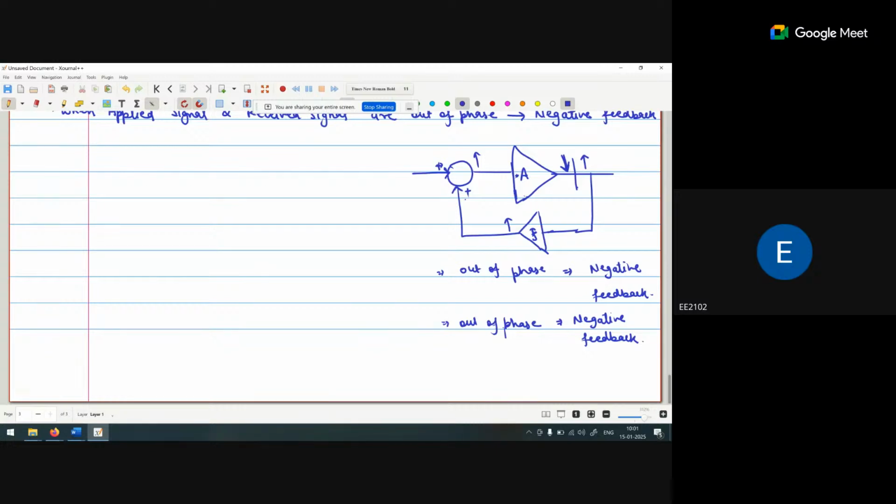When the temperature is 26 degrees, no issue. When the temperature is 25 degrees, no issue. When the temperature is 24 degrees, no issue. After that, if I don't have a feedback system, my AC will be continuously working. So the temperature will keep reducing, and my item, which is suitable for 24 to 26 degrees, will start spoiling. Maybe there is some issue in the food item. So for every controlled environment, for every controlled thing, we have a feedback. Two types of feedback we have, positive and negative.